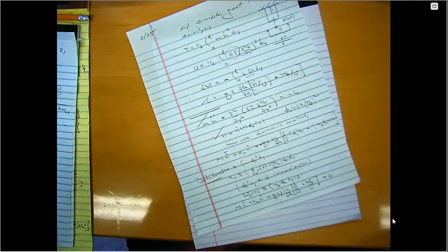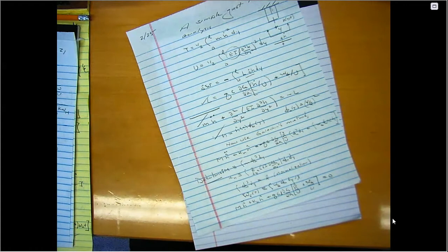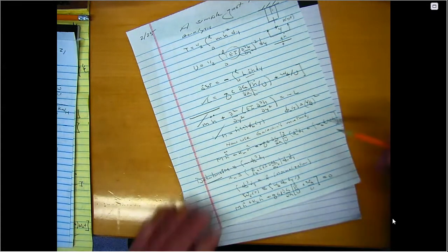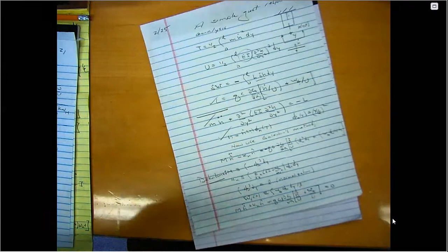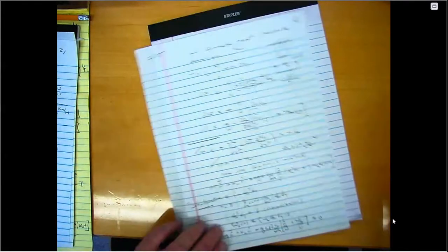Now, there are much more complicated functions involving sines, cosines, sinhs, and coshs, and those are the natural modes of a clamped beam. And probably if you're doing this for the Boeing company or Airbus, you could use those modes. I take this as an example so you have an idea of what these modes might look like. And by the way, look at this. It sort of looks like a parabola, doesn't it? It's sort of like y squared, right? It's pretty close to y squared.